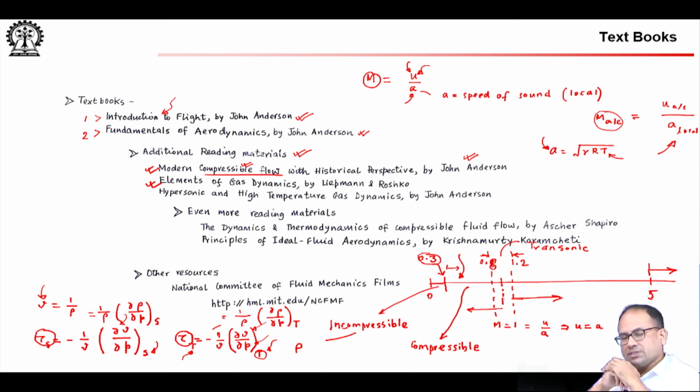In fact, when you look at flow over a body or flow through a duct and you zoom into the flow near the wall, that is where viscous effects are dominant. If you go away from the object into the free stream, you will see that the gradients of velocity are not such that the effects of viscosity will be felt.